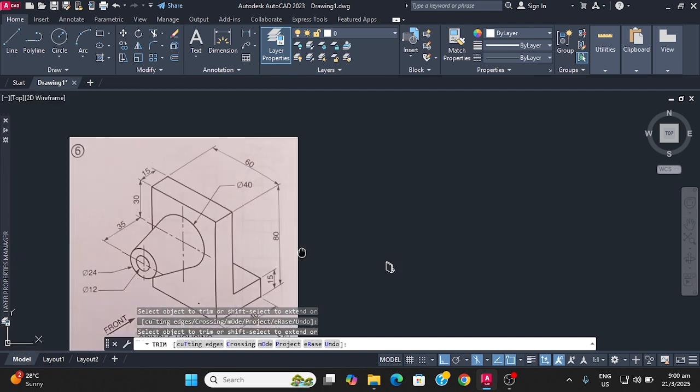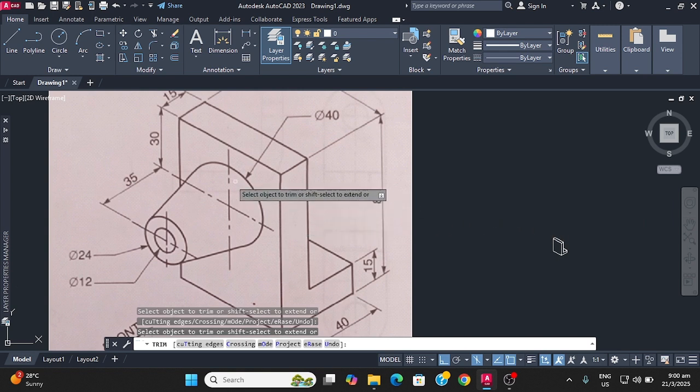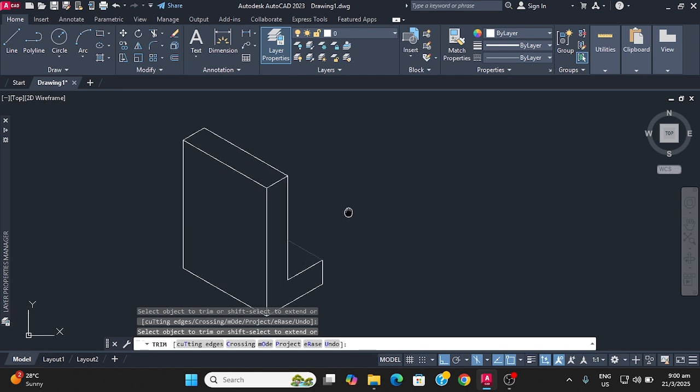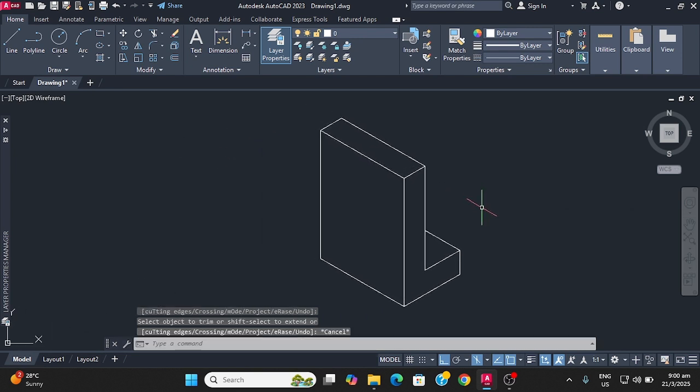So let's look back at this object here again. We need the front part now of the spindle housing. So we're going to be drawing this. First of all, we need to find the center point here. Notice that from the top moving down, we have 30 millimeters down and 35 moving forward. So let's establish the center. We can do that by tracking the point, or we can draw the line. The simplest way for most students to understand is simply to draw the line. So I'm going to be drawing the lines.